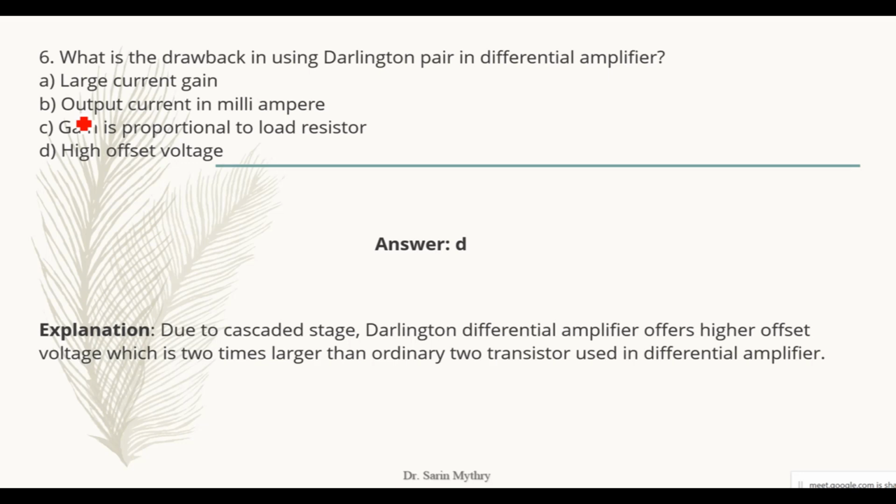if you are trying to find out the voltage gain, we know that at the input terminal, offsets will be present. What is an offset? Offset is nothing else but unwanted noise which is present at the input, even though you do not supply some input signal. That unwanted noise is amplified at the output and you will be getting some output. Means you are not applying any input, but you are getting some output.